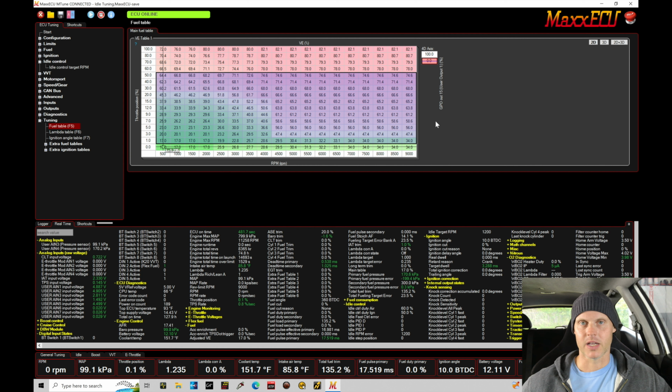0 is when VTEC is off. We have VTEC disabled right now. We're focusing on low cam tuning. We're gonna be dialing this in. So we're gonna be figuring out what our VE values should be in the table to give us proper airflow representation and proper fueling delivery to our engine.